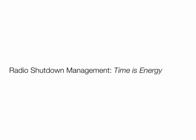If you have a short range link and you are streaming audio, like our Bluetooth headpiece, earphones and things like that, no choice. But in many applications, the traffic is pretty sporadic. It comes once in a blue moon, and in that case, you have an option of doing the shutdown and then optimizing for the power on the receive side.